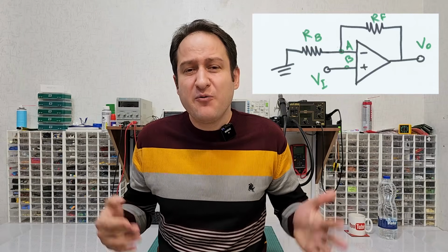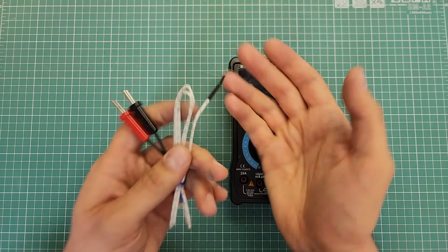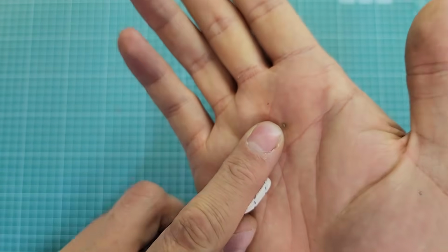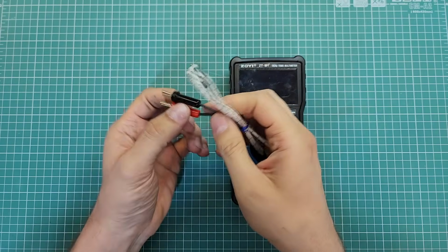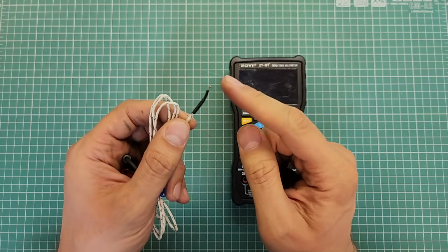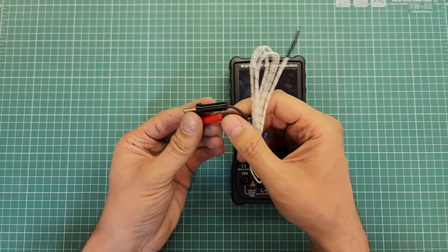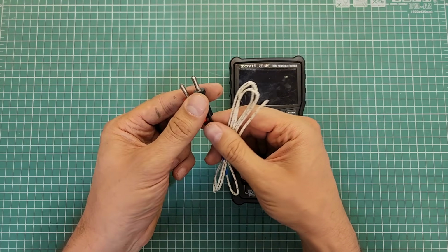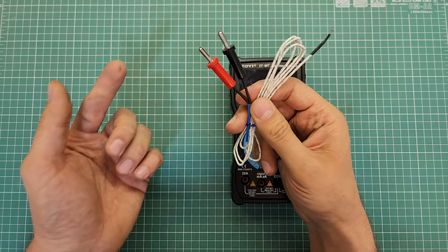You may ask, where is there a tiny and important voltage in a circuit? One of the most common examples is the voltage across a thermocouple. This is a thermocouple. When the temperature at this junction point, look here, increases, the voltage between its leads increases as well. To measure the temperature at this point, we have to read the voltage between its leads and do some calculations to achieve the right temperature. But there is a problem.